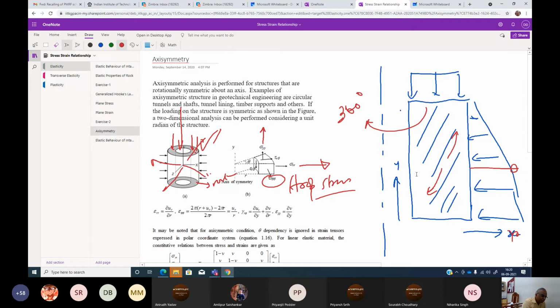So here, the calculation of strain, as you can see, epsilon yy will be del uy by del y. So my displacement is this, and this is the other displacement. Two displacements are there. Epsilon theta theta is basically the hoop strain, and this is the change in the perimeter. This is the original perimeter at any distance r, 2 pi r, and this is with displacement ur.